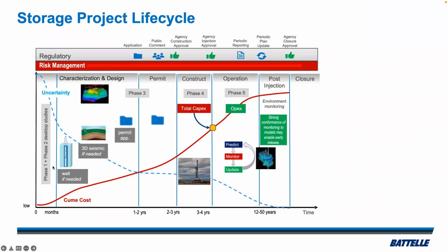So let's talk about well cost. Of course, it's very hard to do that because the well cost will depend on, firstly, how deep you have to drill the well. Secondly, when you drill a well, sometimes you have to do what's called telescoping down. You have to stop part of the way down, cement casing, then drill through it. And sometimes you have to do that multiple times.